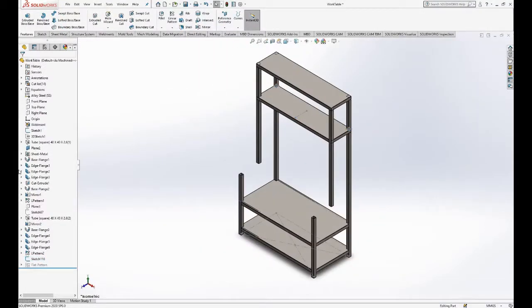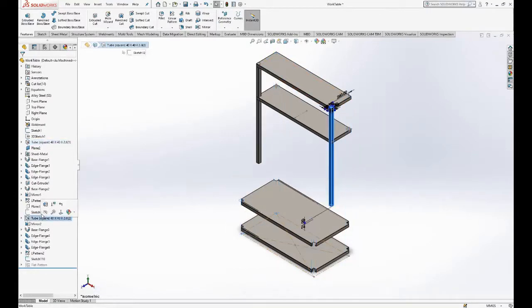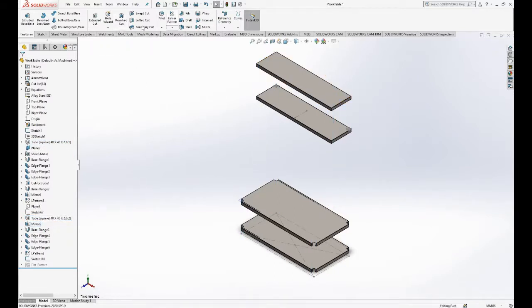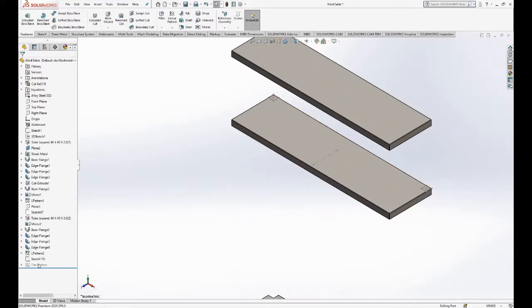Next I want to go ahead and configure the beam height. So I'm just going to double click on the feature itself, find the 203 dimension, go ahead and select on it, and also add in beam height. And we'll add. And those are all the dimensions we're doing for this guy, so we'll go ahead and close out of that. Next we'll take a look at the legs, so we'll go ahead and open them.